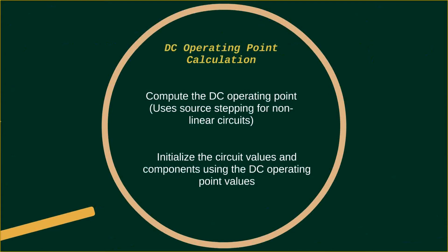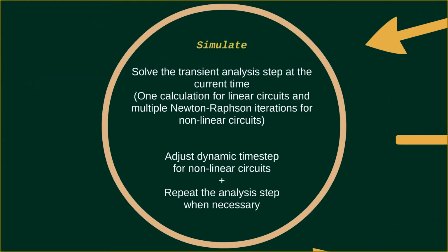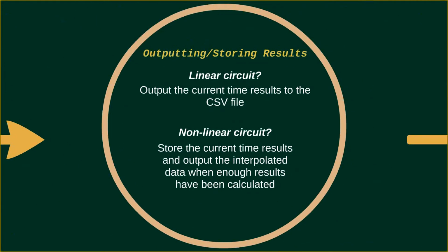Analysis begins by initializing circuit components using the DC operating point. Linear analysis uses fixed time steps, whereas nonlinear uses dynamic time steps to optimize efficiency. To output at regular time intervals, nonlinear analysis must use interpolation as an additional step before outputting.